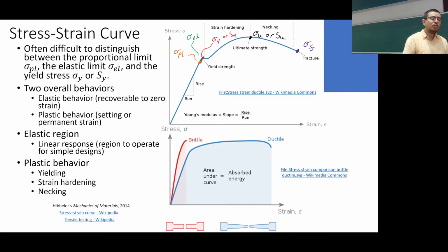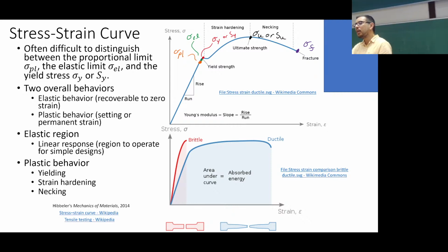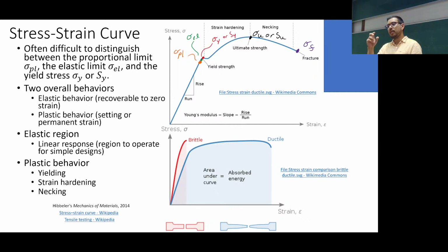We'll get into this. If you're in the plastic region, then yes, it does enhance its strength. One of the interesting things about structures and steel, and you'll learn this in this class: often the highest stresses, for a bar, we say everything's uniform in the bar. But for shafts that twist and for beams that bend, the highest stresses are actually at the surface.